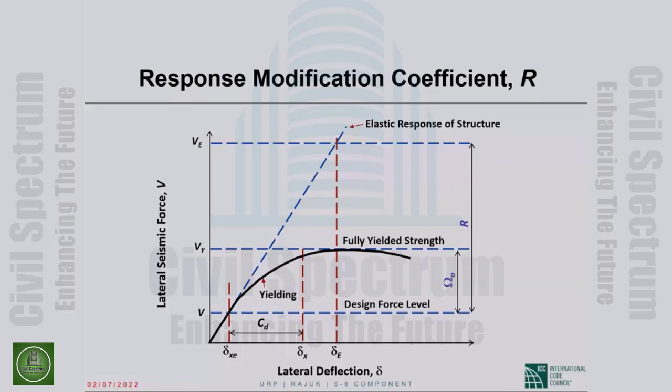If we want to figure out the largest bending moment that can be developed at this section, if the design earthquake were actually to hit, our estimate of that maximum moment would be omega sub 0 times the 100 foot kips negative. Okay.